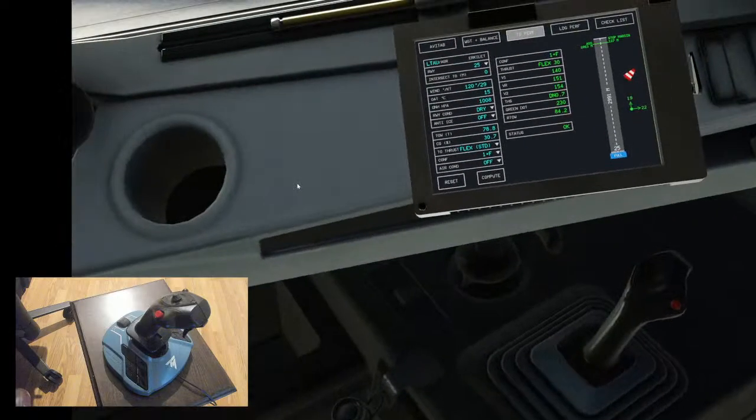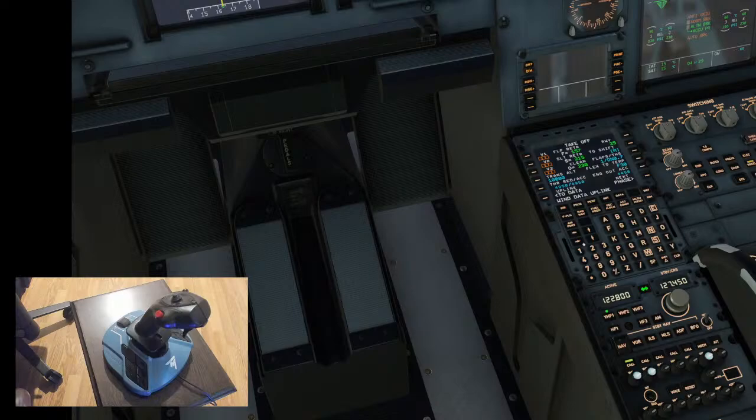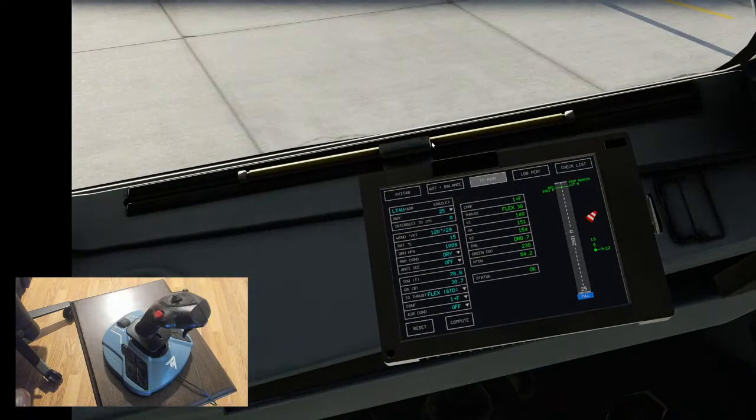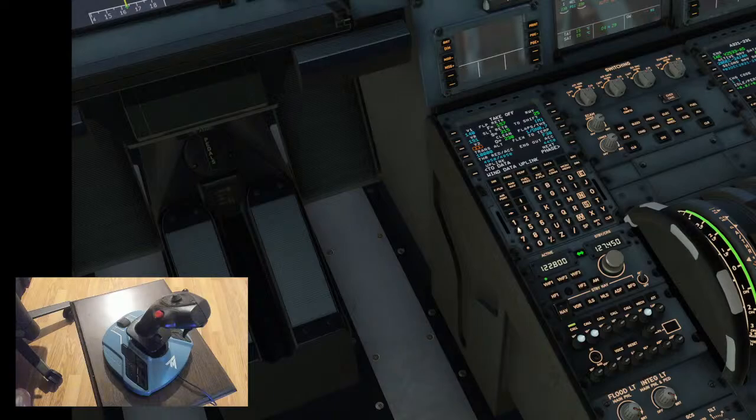Yes. And our critical speeds are 140 knots, 151 knots and 154 knots, which means we will rotate at 150 knots. And 154 knots V2, which means that even if we lose one engine, we can continue to climb, take off, and we can turn back.